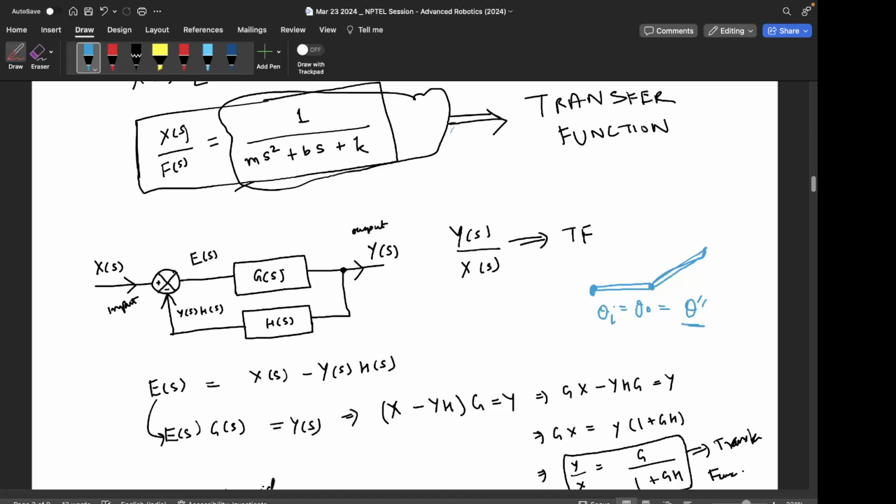And then we will start giving our trajectory. We will give a new theta input for the first time. The control will generate some torque, it will be applied, and then we get the updated theta output, and then the loop will start. So you can do it like this also, initialize both input and output to the value of the initial states, basically. If you know that, you can initialize both of them with that value.